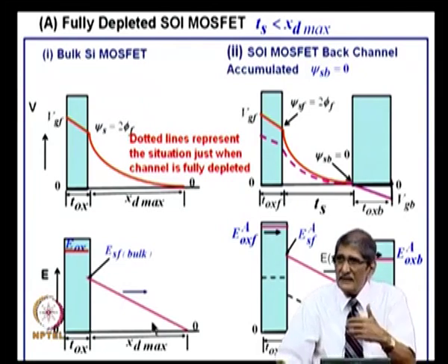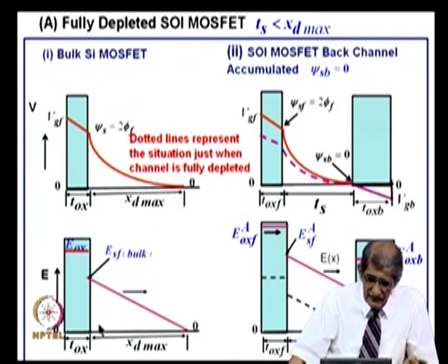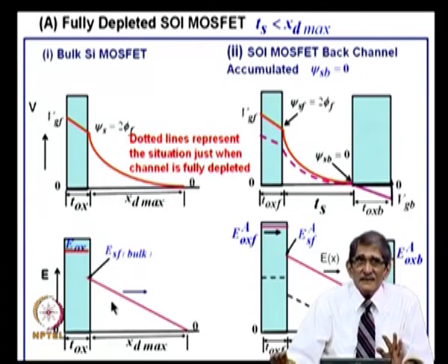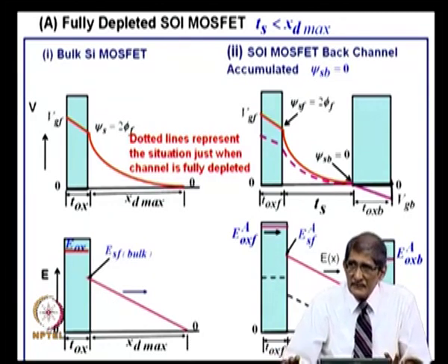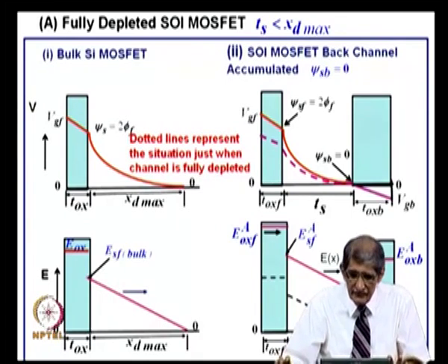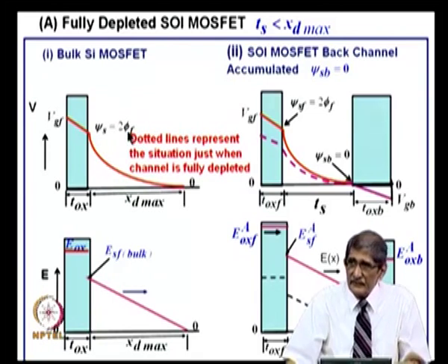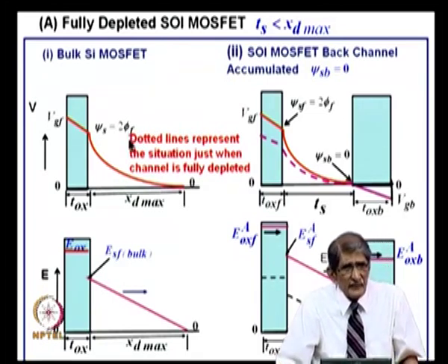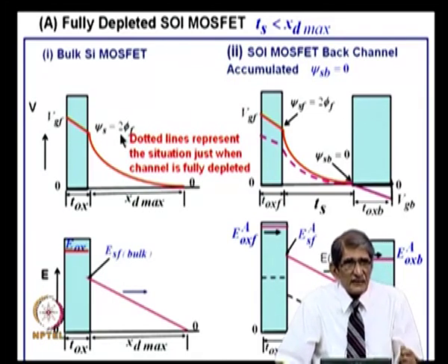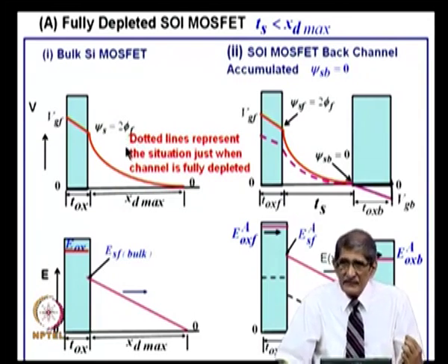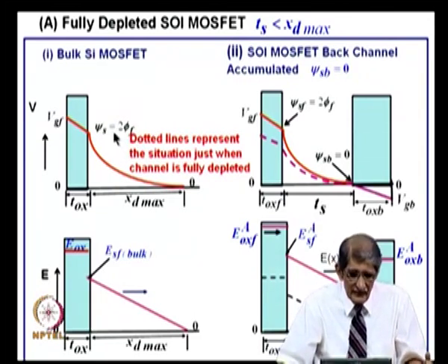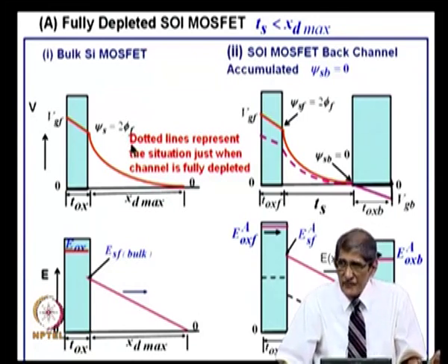We have seen it a number of times. So, this is the extreme maximum. At inversion, we are considering threshold voltage. So, we are considering a situation where there is inversion. That means, we are considering a situation where the surface potential, that is the potential at the surface of the silicon, is 2 psi_f. I think in the previous series of lectures you would have called that 2 psi_B. Sometimes people call it 2 psi_B, I call it 2 psi_f. Both are the same. Okay.